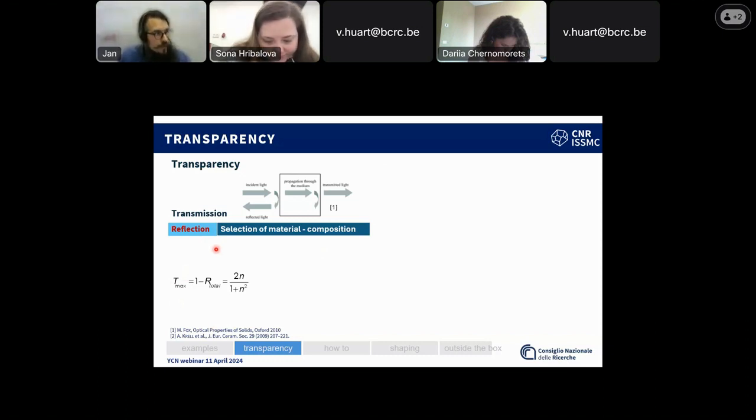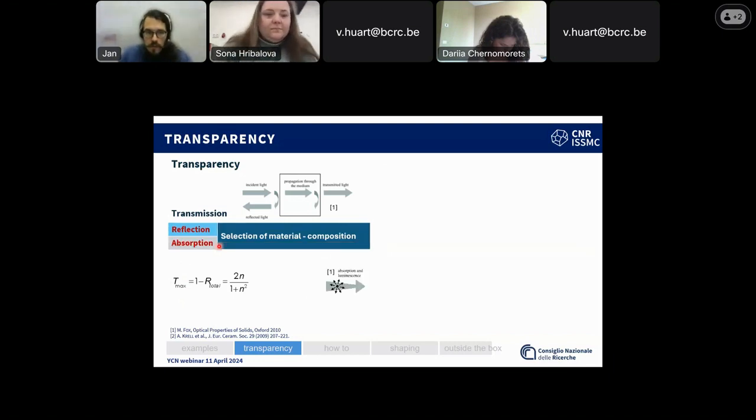It might get a bit more problematic if you start with, let's say, more dissimilar materials, where it's not just, okay, I changed 1% of the whole composition and it's another base. This is something that we addressed in scintillators, where we're combining two different garnets, gadolinium gallium aluminium garnet, and yttrium aluminum garnet. The problem is they can't be sintered at the same conditions.